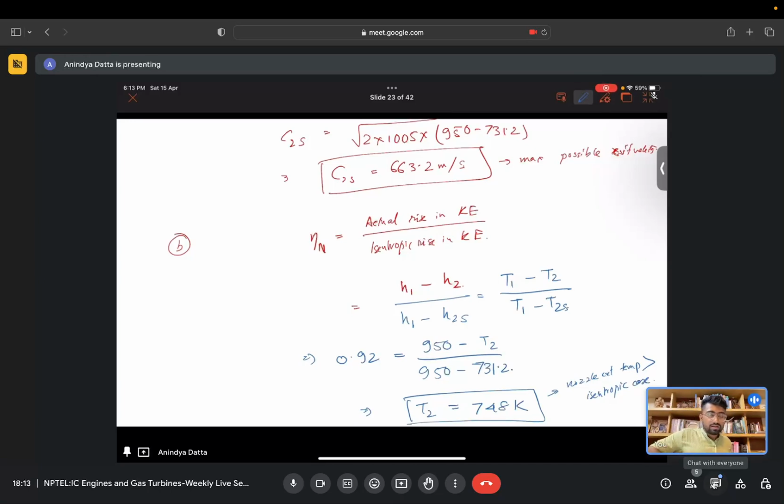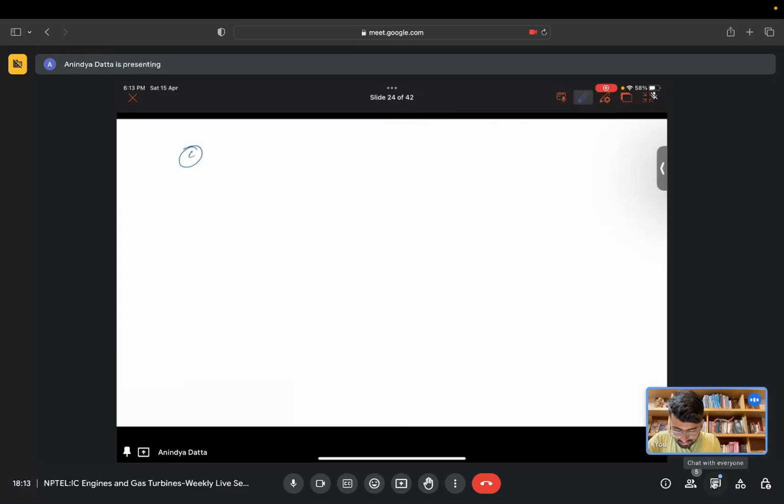Okay, this is because of the flow irreversibilities. Because of flow irreversibilities, we are not able to achieve the lower temperature and higher velocity. We will see that the final velocity at the exit of the nozzle is also lower. Because of the flow irreversibilities, viscosity and other factors, the flow is getting slightly heated up compared to the isentropic case. Okay, so option C is the last option.